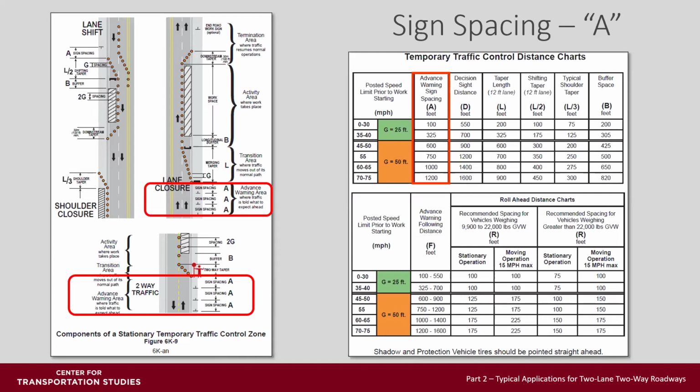Remember, these distances may need to be adjusted for intersections, driveways, curves, hills, and other conditions. Typically, you increase those distances to provide additional time for drivers to react.